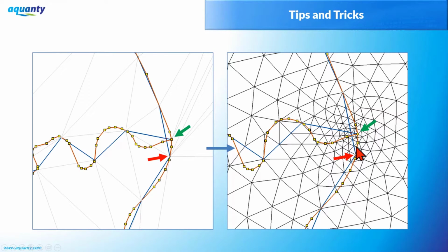Another problem that can pop up, this itself is not a snapping problem. These are actually snapped together. However, the problem here is that this segment is not split at the actual junction location. So this is one continuous input segment, and this is a separate one. This is something, say, that could happen at your boundary, where your streams meet your boundaries, something along those lines.